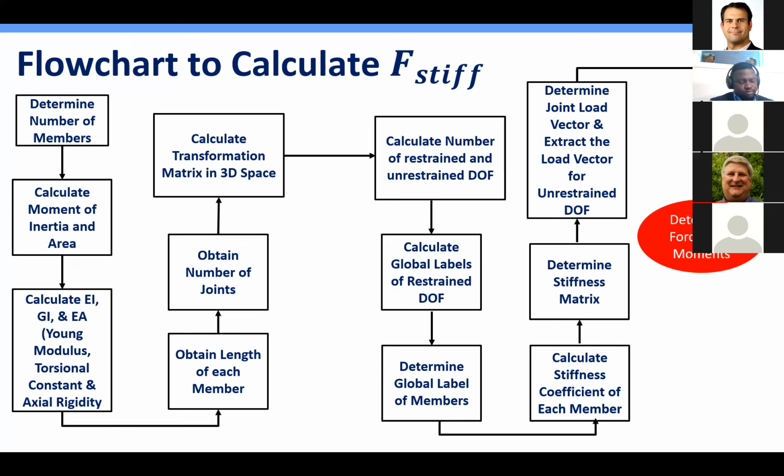Yep. Well, in fact, we had a well several years ago where the soft string model did not pick up the difference between pick up and slack off. There was quite a bit of asymmetry between the neutral value and the pickup and the slack off, which we attributed to stiff string. We did not have high resolution data in that initial case, and based on some assumptions that we made, we had to add a simulated high resolution survey data, which had a spiral in it. It was borehole spiraling.